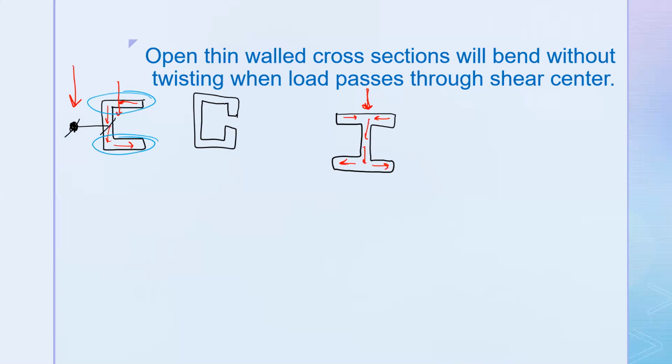And the way that we locate our shear center is by integrating our shear flow to figure out the amount of moment. And then we place our load P, our applied point load, such that the moment is the same from that point load and from the shear flowing arrows that we've drawn. So you know it's going to be on the left because these arrows that we've drawn create counterclockwise moment, which is what we want to see. Putting the P over to the left also gives us that counterclockwise moment.